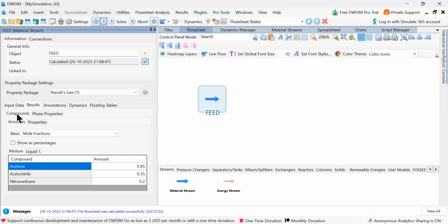Let us summarize. What are we trying to see? For a particular ternary system, temperature is given as 80 degrees centigrade, and it is asked to find L, that means liquid flow, vapor flow, and their compositions. So first of all, we need to check whether the given pressure falls between bubble point pressure and dew point pressure. That's what we have calculated. We will see in the next class how to calculate bubble point temperature and dew point temperature with another example.